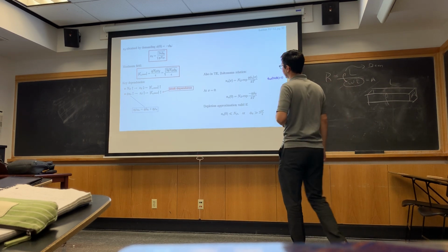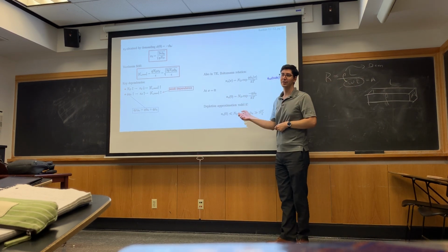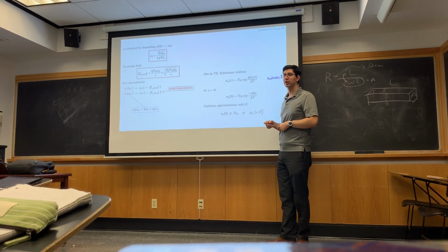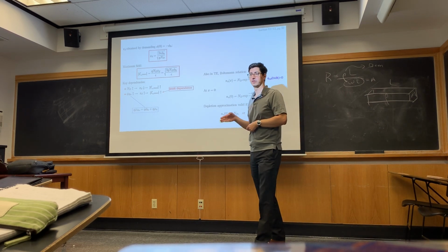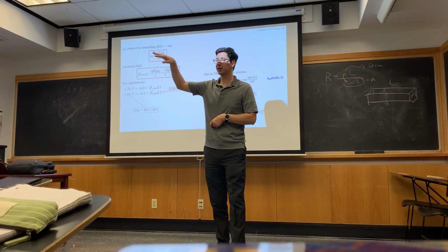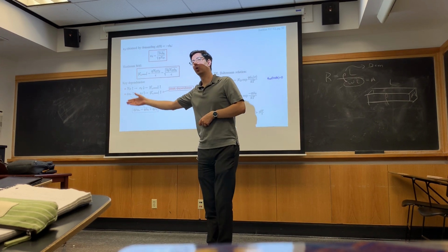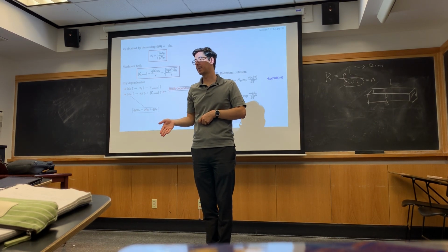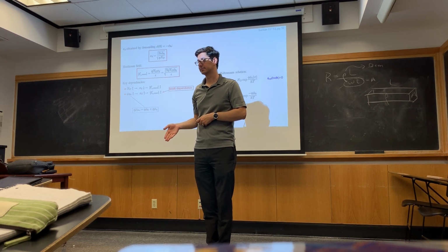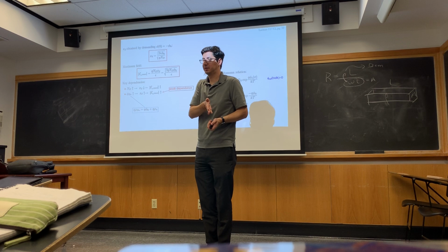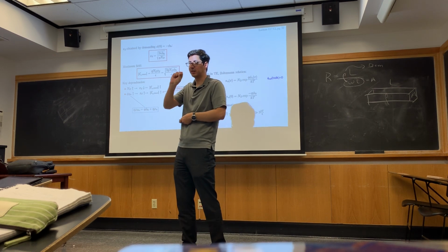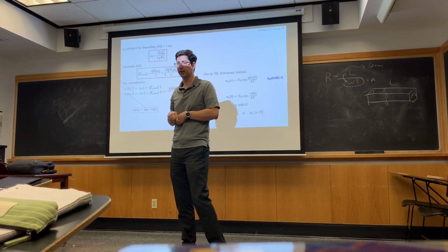What is my electron concentration at 0? Well, I know what my electron concentration is in the bulk. It's just equal to ND. And I know my potential difference going from the bulk to the surface is phi bi. That's how much potential drop had to change, because we're saying there's basically no potential drop on the metal side.